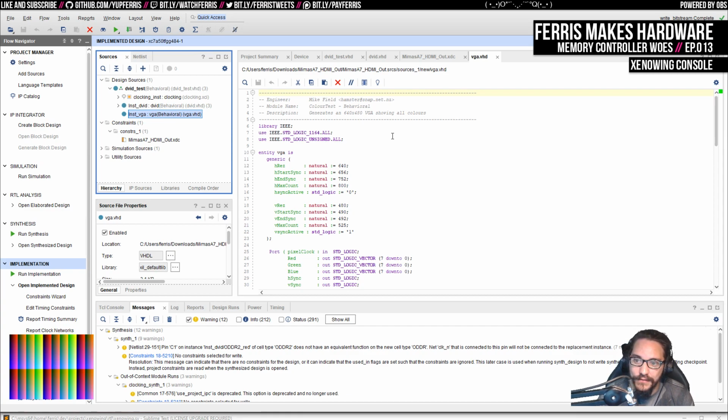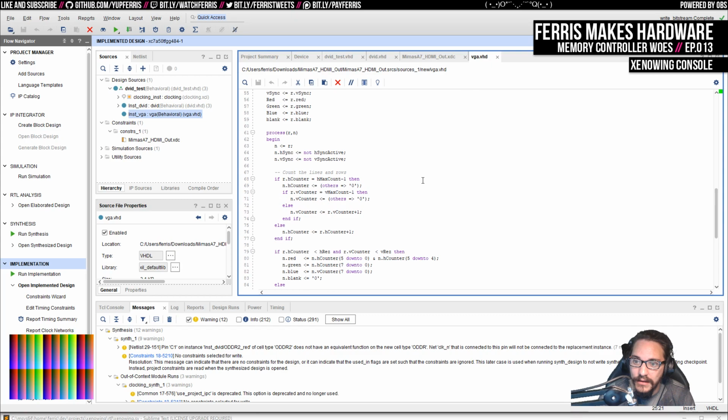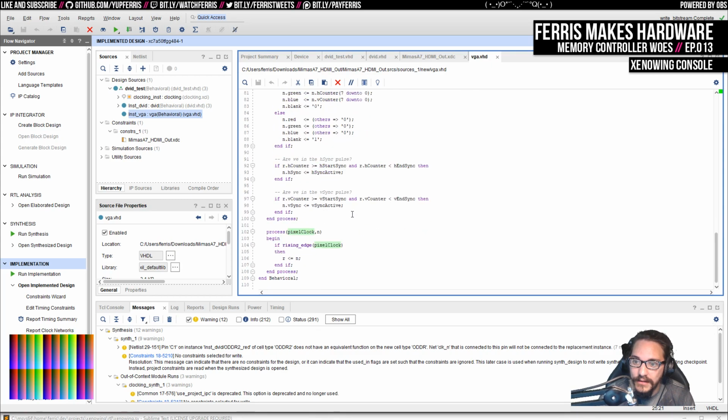And I guess if I read this correctly, then this pixel clock registers all those in the next one here. If I have a clock that's say 200 megahertz and it's phase adjusted such that this 125 megahertz signal matches, it might be safe.